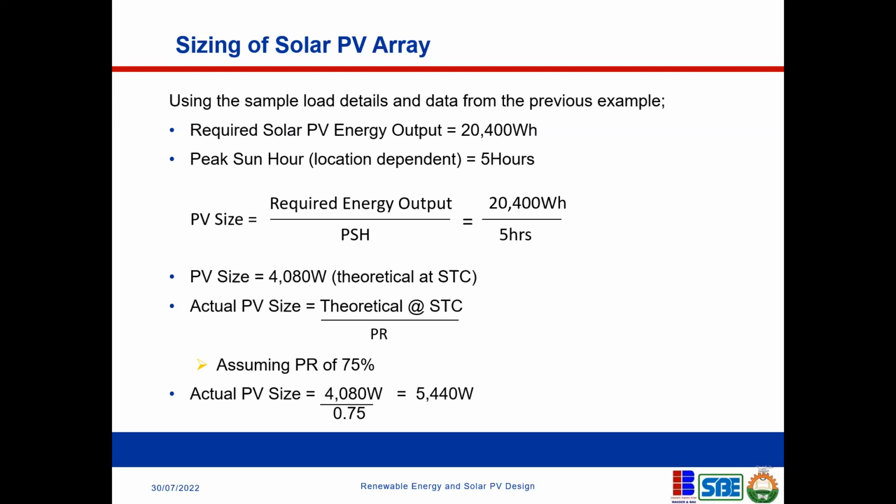For a PV system that has up to a 25-year lifespan, it does not mean that after 25 years it will no longer produce electricity. It will still produce electricity, but the performance will have gone down to about 80 or 70%. The same thing happens with your battery. Every time you charge and discharge your battery, it counts as one cycle.